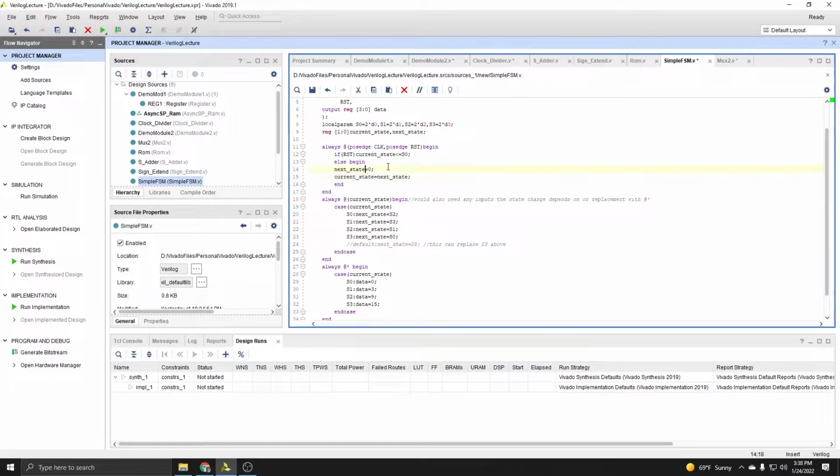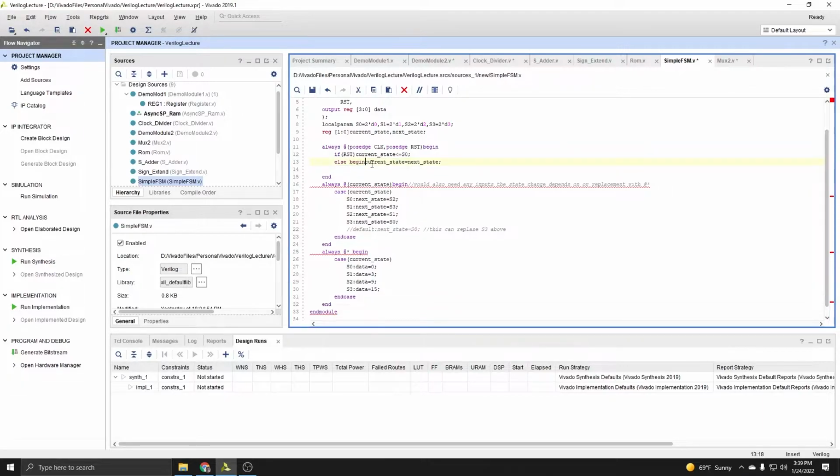So basically, the rule of thumb is whenever you're working with sequential logic, like a memory or a register or any of the above, you're using non-blocking for sequential and blocking for combinational. It just allows you to simulate that ability of storage, and how alterations to it do not affect the next operation.